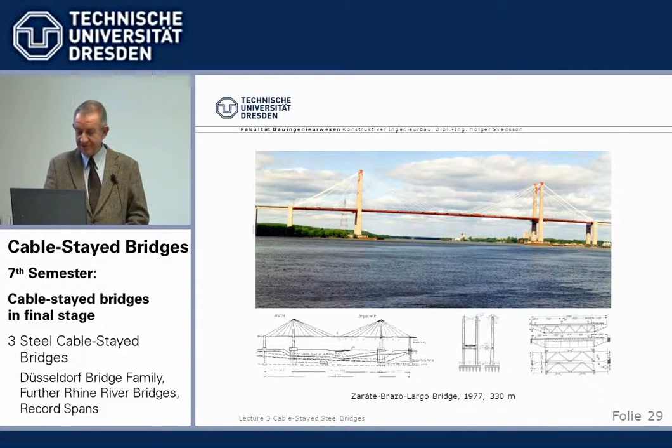The first major cable-stayed bridge for full railway loading in Argentina. Two identical bridges, actually, that's near Buenos Aires, between the cities of Zárate and Brazo Largo, 330 meters, one-sided for heavy ore, Cooper 80. Railway makes it quite unsymmetric transversely. An important bridge with many new ideas.